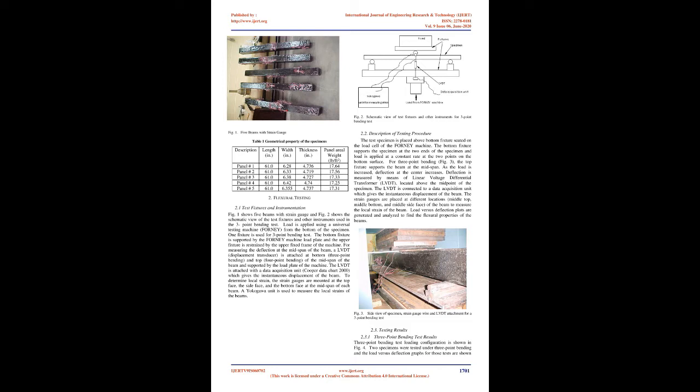Innovative fiber-reinforced polymer, FRP, composite highway bridge deck systems are gradually gaining acceptance in replacing damaged or deteriorated concrete and timber decks [5]. FRP bridge decks can be designed to meet the American Association of State Highway and Transportation Officials, AASHTO, HS25 load requirements [5].